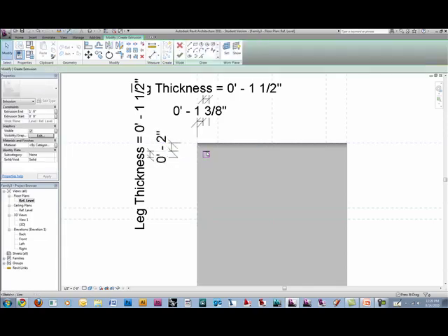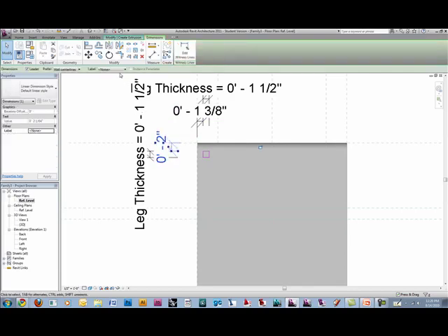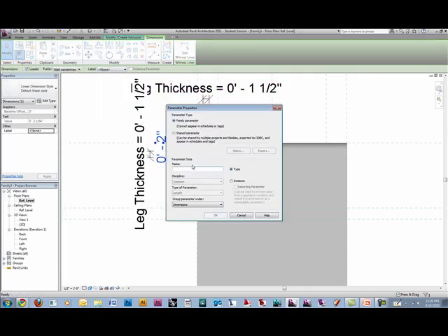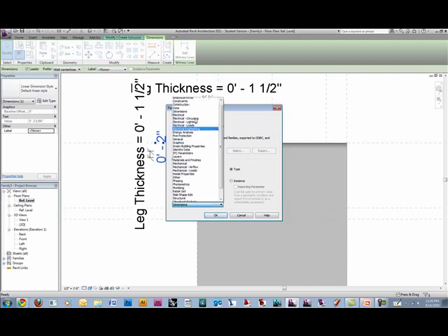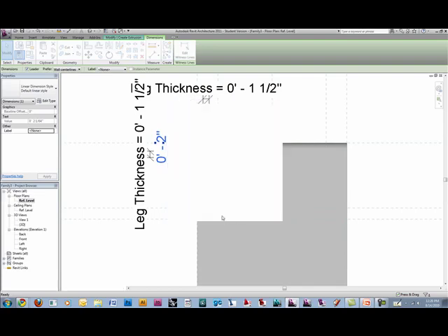So maybe I like the 2-inch offset because you have to remember we have a 1.5 inch roundover. So we can't put it up in the roundover. This is where I'm going to do this one first, that way the other one will automatically snap to it. So this is going to be the leg offset. And this to me is a constraint, not a dimension.